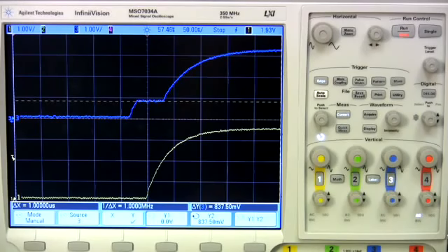This demonstrates the SI8405 anti-latch circuit in action. Relative to typical I2C clock frequency of 400 kilohertz, the approximate 30 nanosecond delay in the B side transition and added 30 nanosecond delay until this propagates back to the A side is very acceptable.